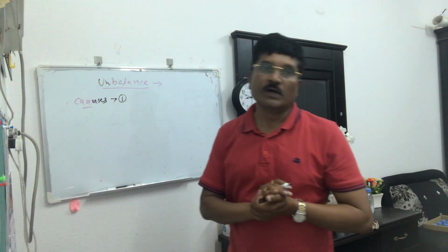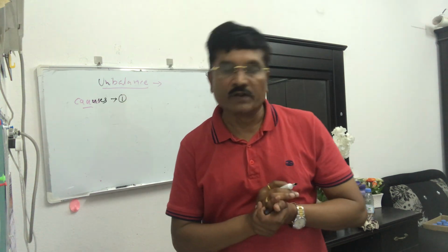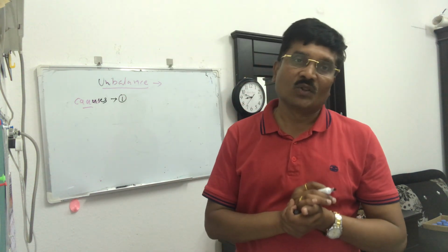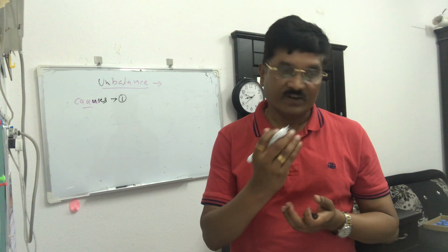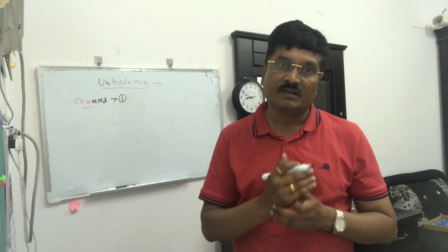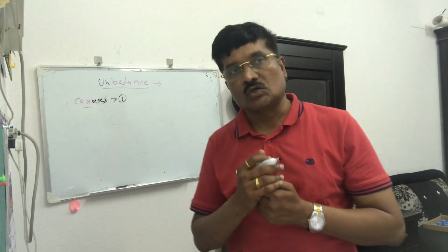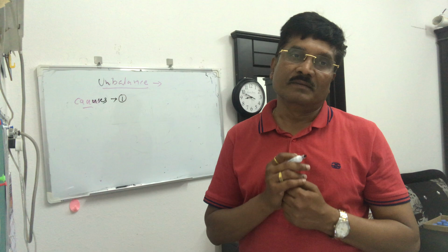First one is manufacturing defects. While machining or while preparing some rotary part, there are always some tolerances in the manufacturing field, like they have casting, they machine it. If it is not machined in a proper way or in proper tolerances, then it creates unbalance.